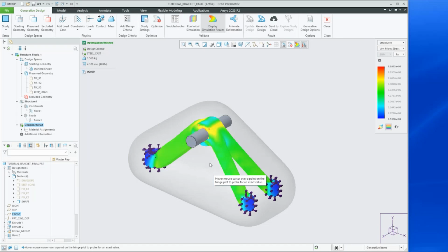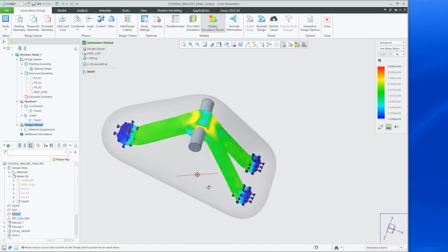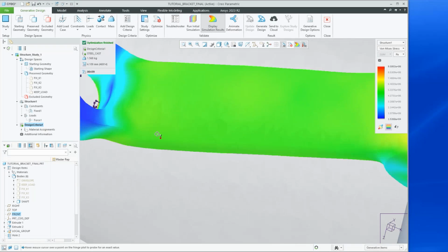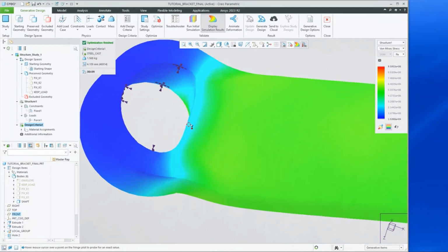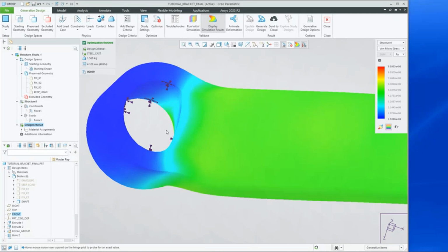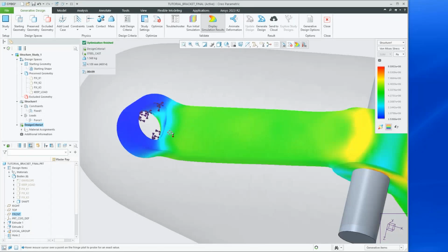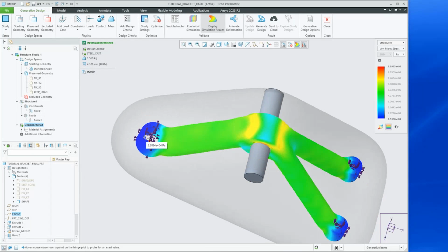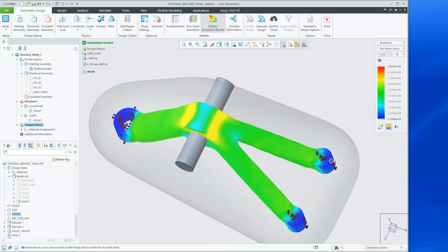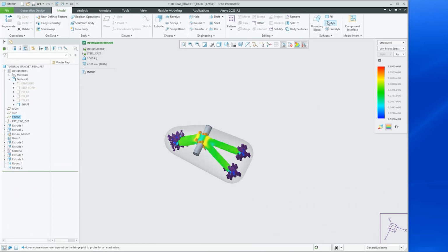So if you want to control this, you actually need to create, say for instance, you want there to be a nice clean hole. Now, probably you can see here, the optimized geometry is actually spread into the hole here. So this is obviously not what you'd want. This is why we would need in this case to create an excluded geometry, and we would need to create a cylindrical region through each of these mounting holes that was an excluded geometry.